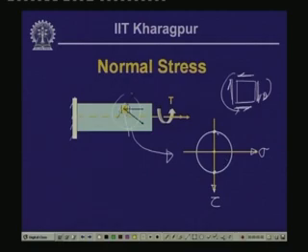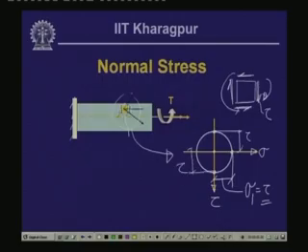Now, if we plot the circle, then this is the Mohr circle of the stress, and this particular point on the Mohr circle represents the plane where we have the maximum normal stress. This we call sigma 1, and incidentally its value is equal to tau. If tau is the shearing stress, this is tau, this is also tau, which is the radius of the circle, and since normal stress is 0 here, which is a state of pure shear, the normal stress is equal to tau.